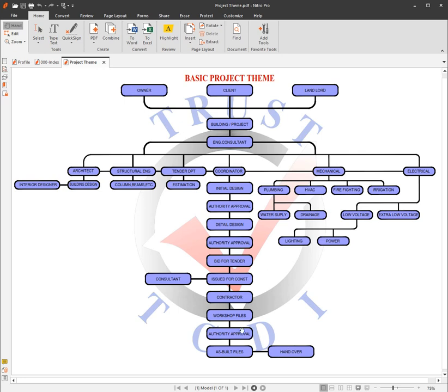First of all he has to prepare workshop drawings, because the drawing designed by the consultant is just for information, for quantity, for materials, and just for an idea. Accurate design is done in the stage of workshop drawings, which we call workshop files, or shop drawings as well.